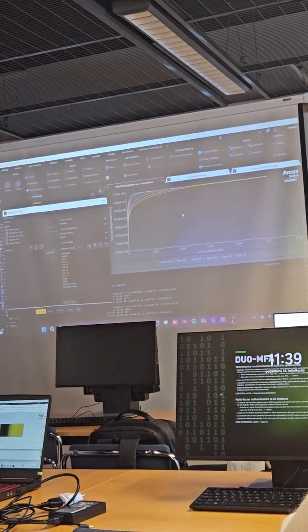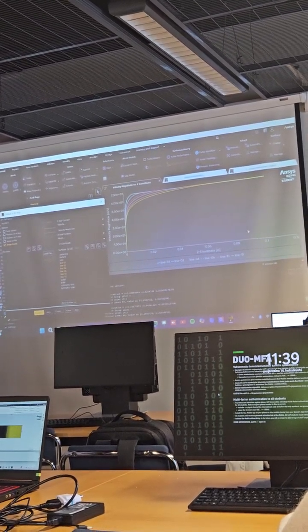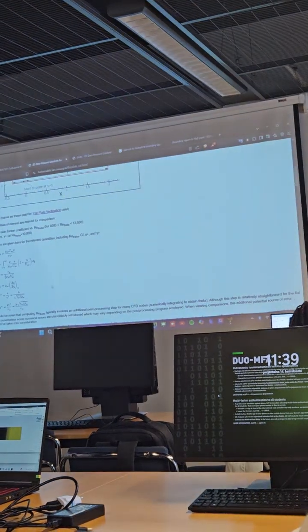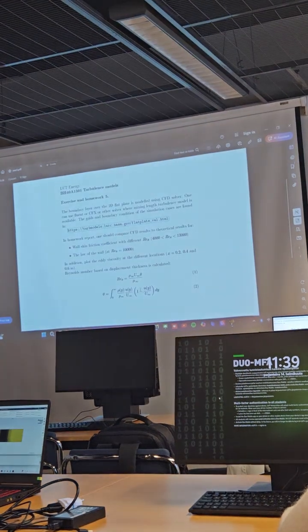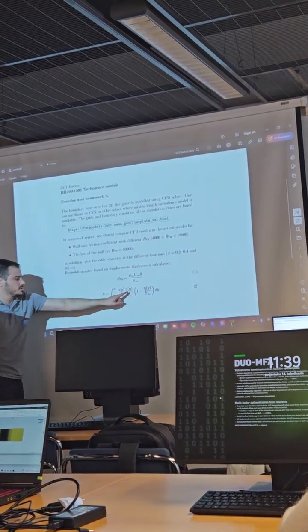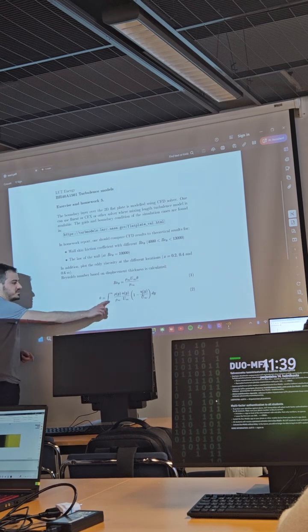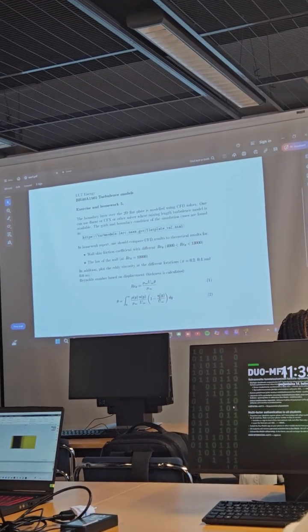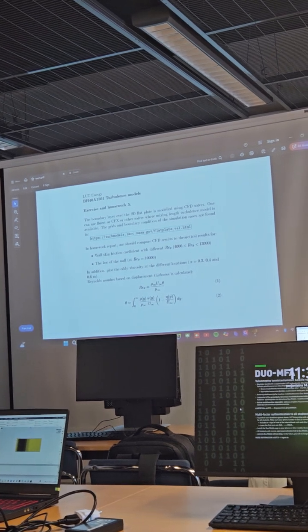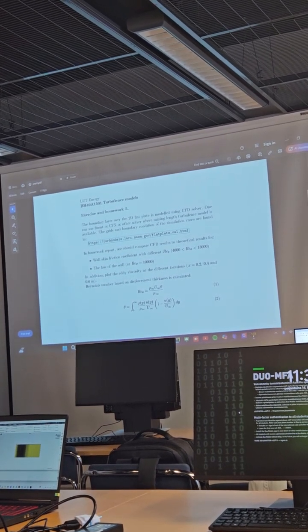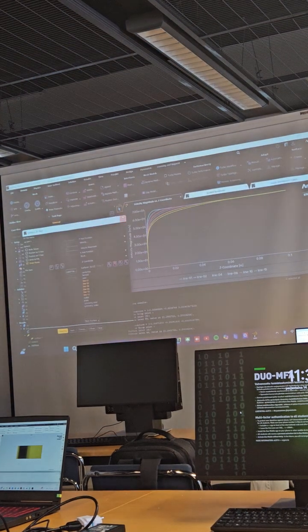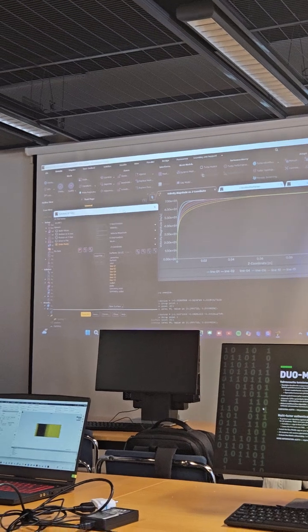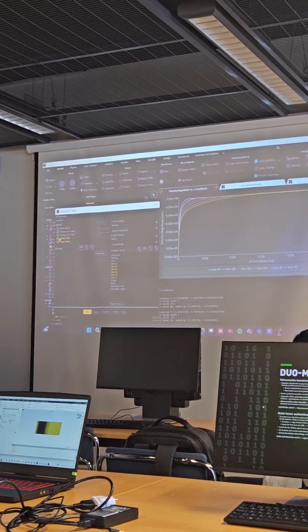So these are the velocity distributions at those lines, and we need them to calculate this integral. Because in this case, for this equation, we need u as a function of y, that for our simulation is z. So y is the distance from the wall. So we can post-process them in Excel. So we can write to file.